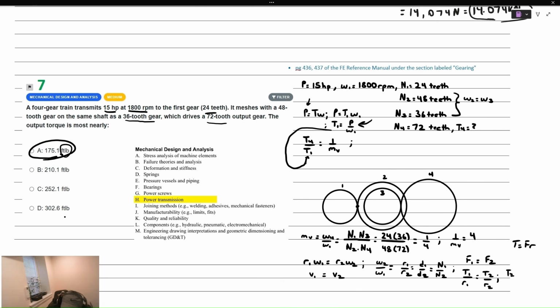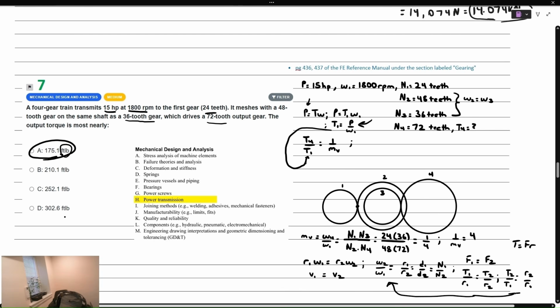We can solve for the ratio of the output torque to the input torque, and what we end up getting is R2 over R1. Notice that's just a reciprocal of what we saw for the angular speed relationship. This is over here, right? So the angular speed and the torque, their ratios are related via reciprocals. And we could travel down the gear system and be able to find the gear ratio like that, or we can do it using the idea of driven and driving gears.